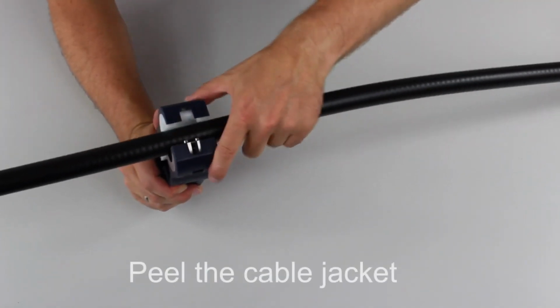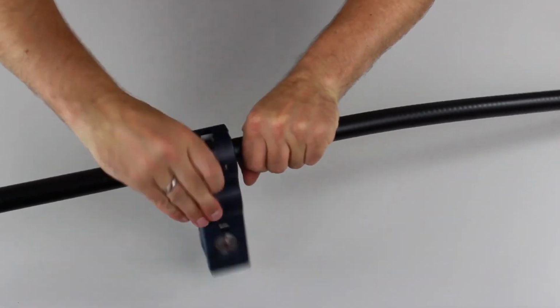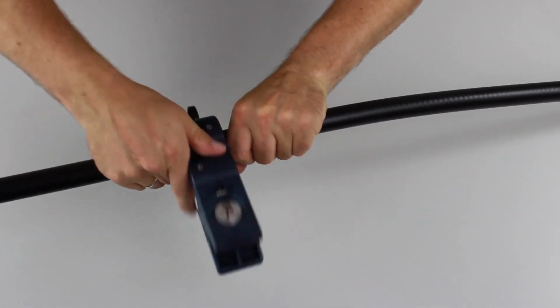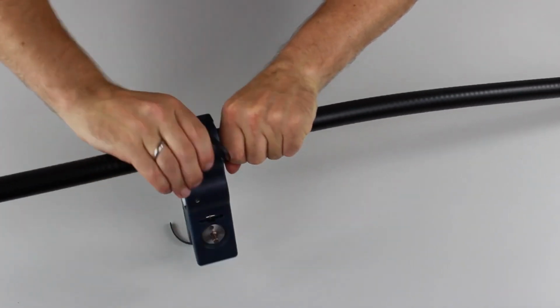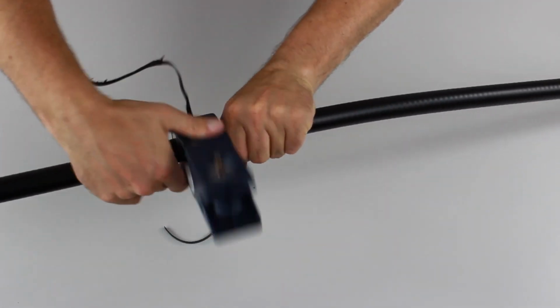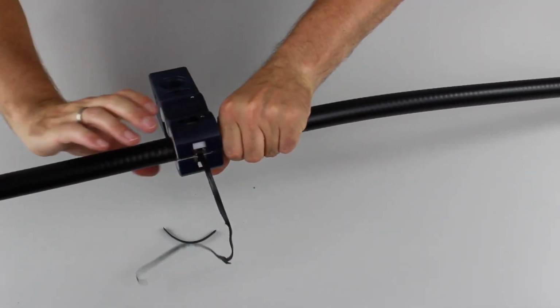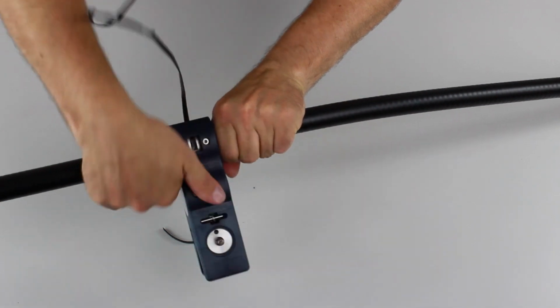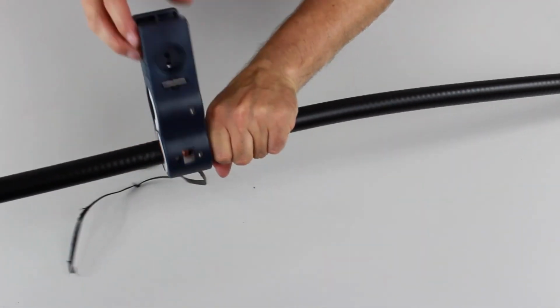Using the peeling tool on your Uni-Prep tool, peel the sheath at the required location on the cable by running it once around the cable and then apply a slight forward feeding motion. Continue until you can see the outer conductor protruding slightly and you have peeled the sheath for a length of around 24 to 28 millimeters.